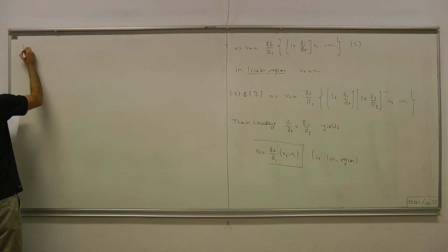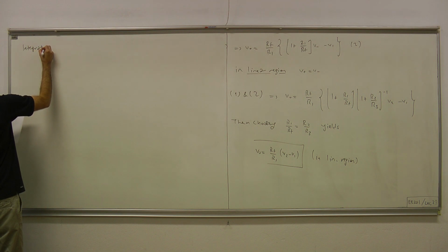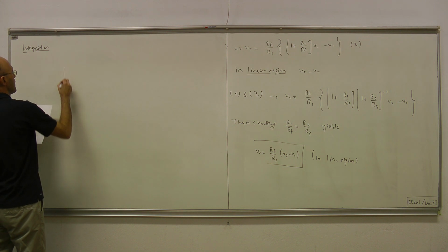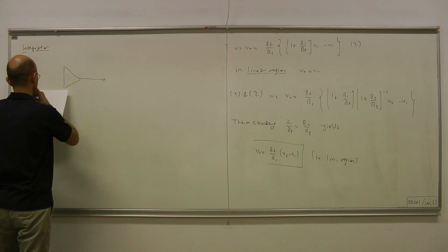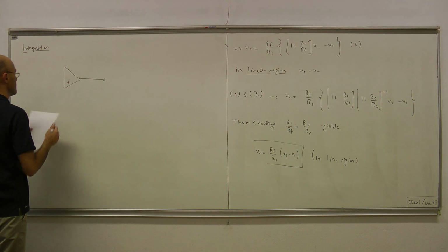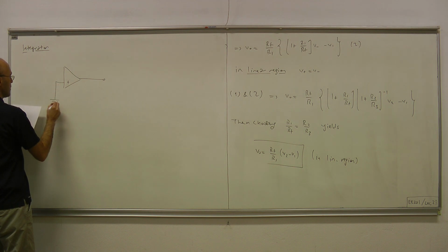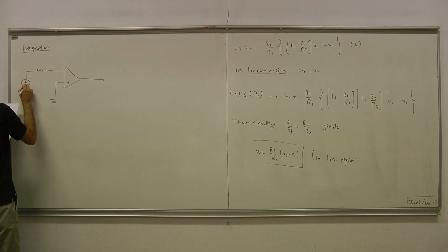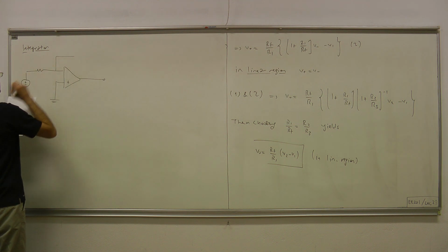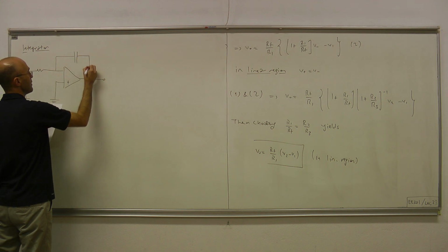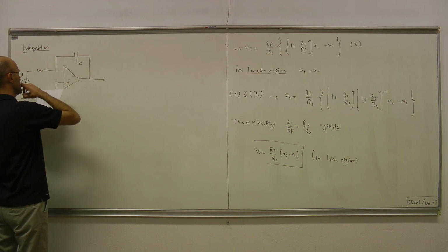Okay. Let's begin by building an integrator, which requires that we use a dynamic component, namely a capacitor. Now in the feedback connection, instead of a resistor, we place an LTI capacitor with capacitance C.